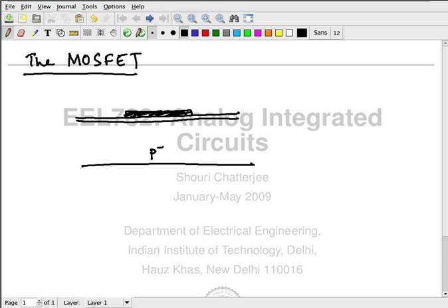And then you are going to remove the oxide. Now, where the oxide is shielded by the polysilicon, you are not going to be able to remove the oxide. Otherwise, you remove the oxide. So basically, you remove this line, and it looks like this.